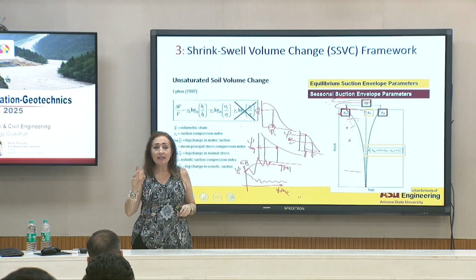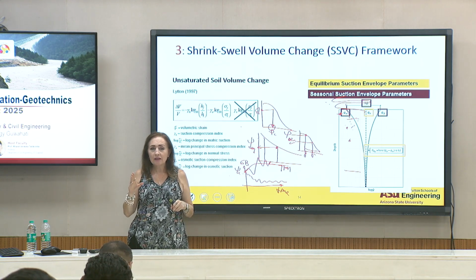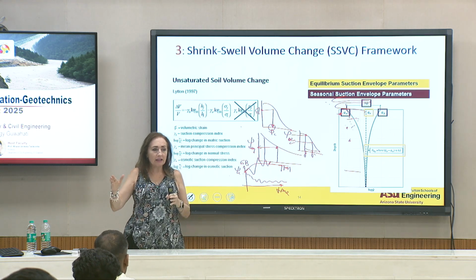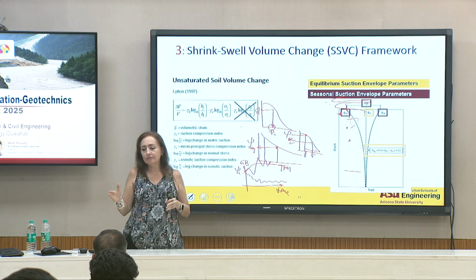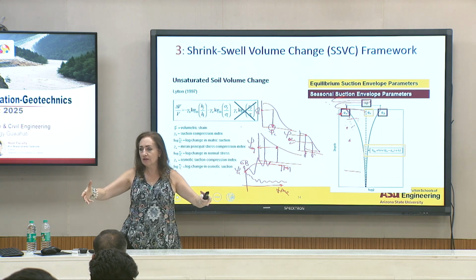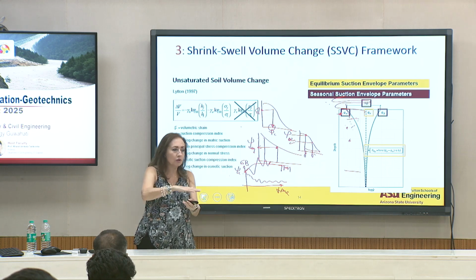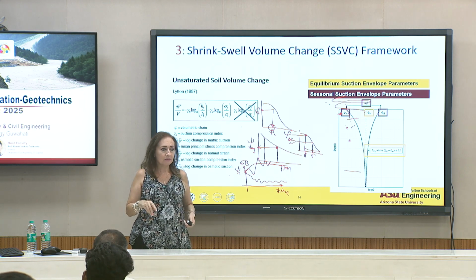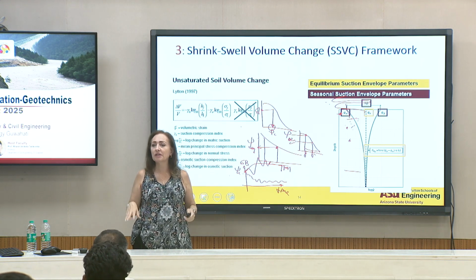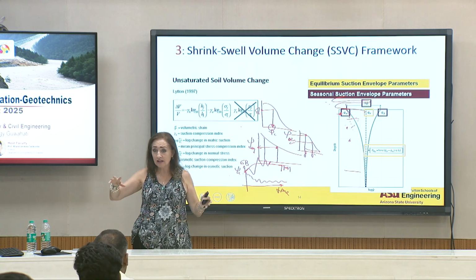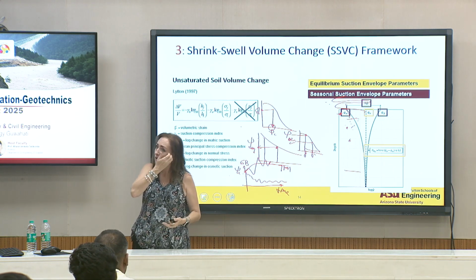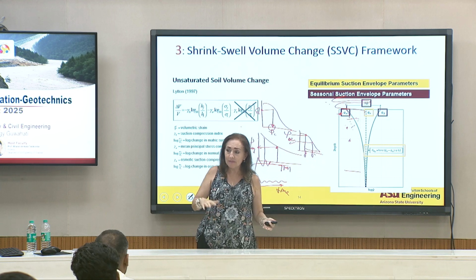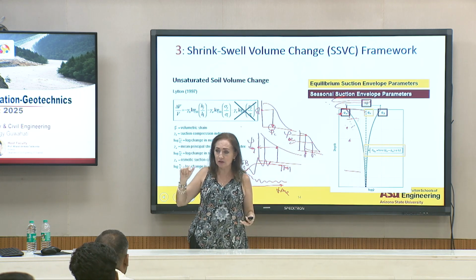What happens in practical engineering is, okay, I'm going to be making a slab on ground for expansive soils, and we go to the laboratory and do a free swelling test. And we say this soil's expansivity is going to be 13%, and then they need to work with that to do the slab on grade. This is a maximum value that we get in the lab. That's a limit value that we have.